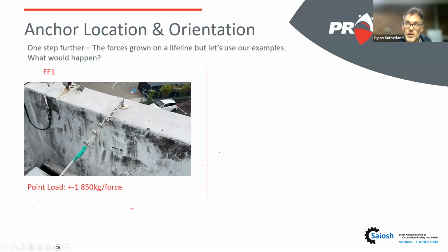Because this is not a certified system, the probability is the hook will break, or the turnbuckle and the cable will fight each other in that fall, and something will give in, something will break. And ultimately, the human will break because they will hit the ground, which is not okay because that's not the person that decided to use that system. They were just told to use it.